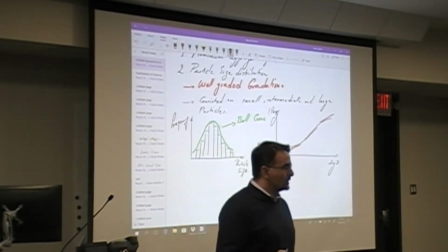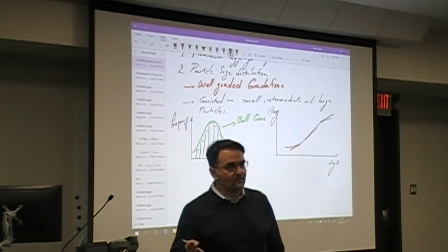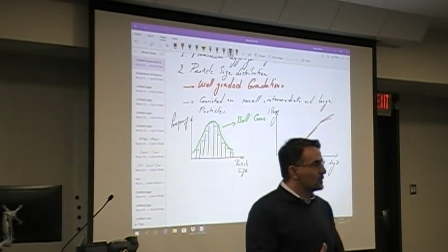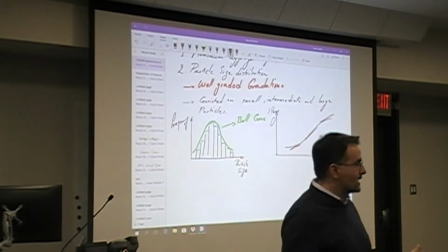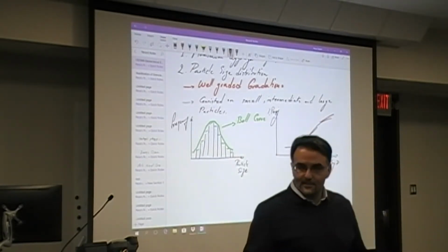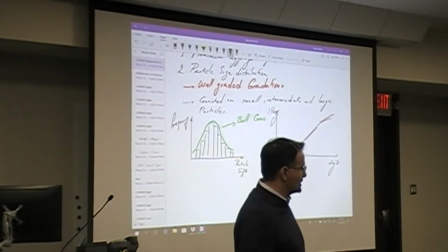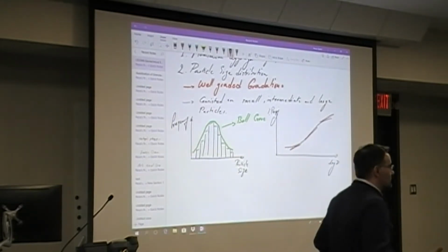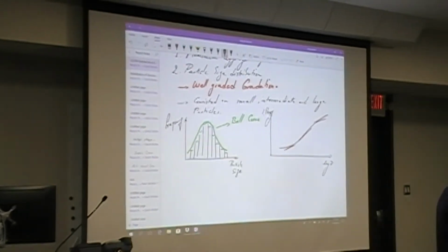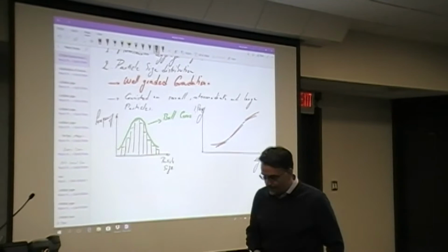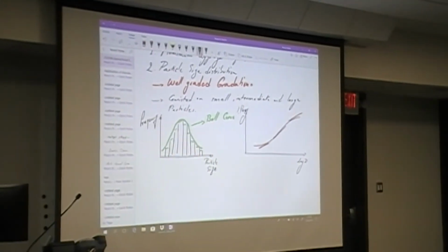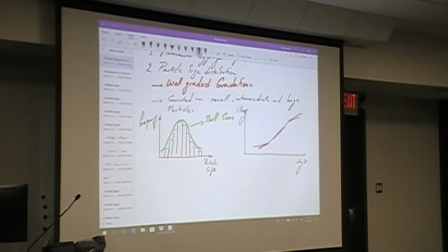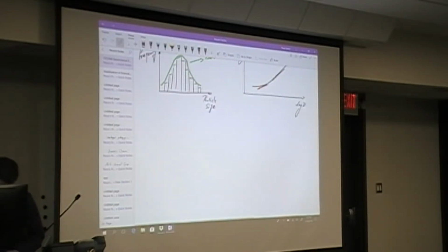In very simple terms, anywhere that you expect load bearing, right? Any instance of when you need to have a robust platform, you use a well-graded material. All right. So that was very simple and straightforward. Now let's talk about the poorly graded material and see how we can characterize this one.